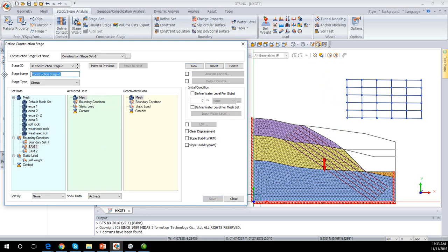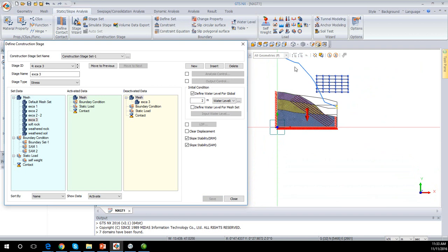And lastly, I'll go to my third excavation. So I drag and drop the last set. I will now actually simulate what would be the water level. So I can select the water level I had defined previously, the set of geometry, and this value now becomes a multiplier. So I give it a value of 1, and lastly activate these sets. And so we see here when I click save, we can see a small blue line appear. If I was to give this a different value, for instance a value of 2, it's a multiplier. We see that it follows the same geometry more or less, but it's now amplified, or vice versa if I gave it 0.5 or something.